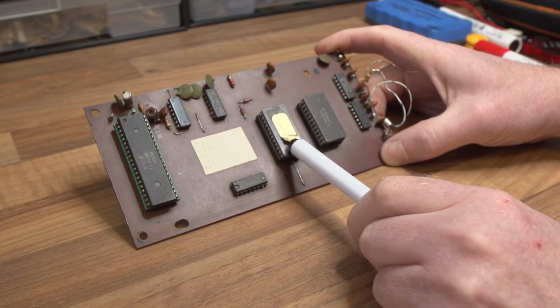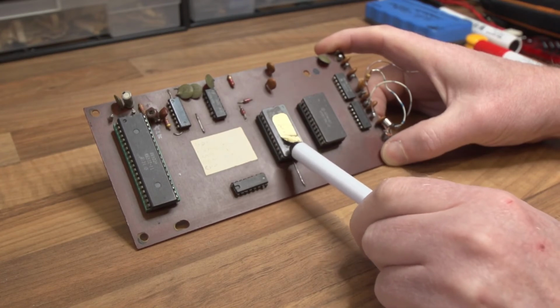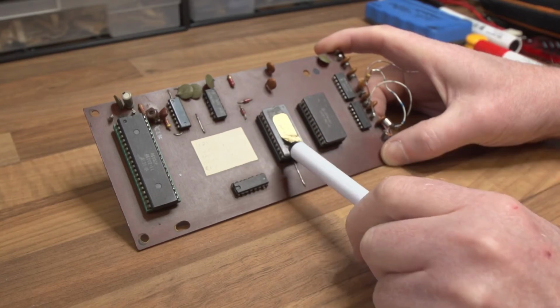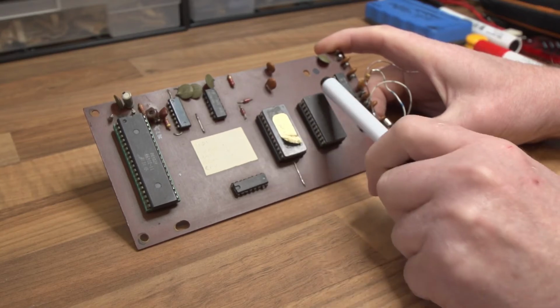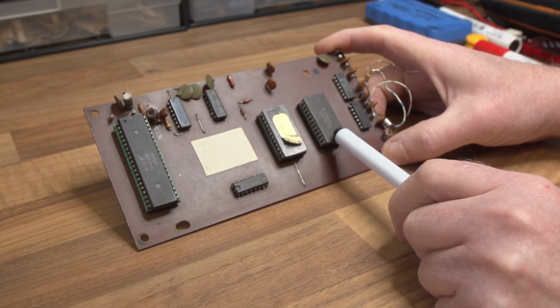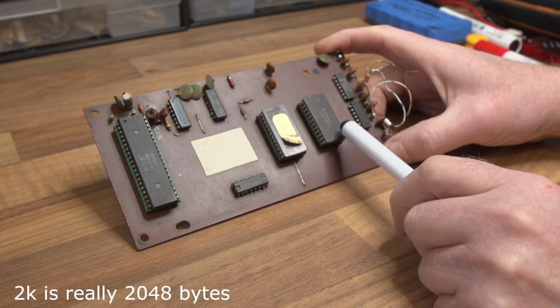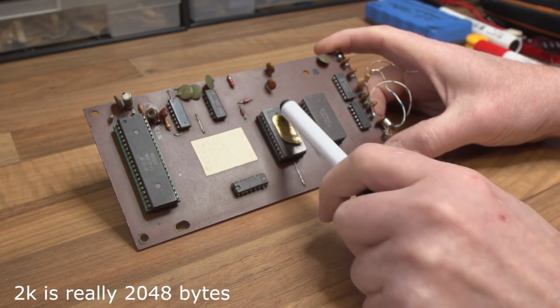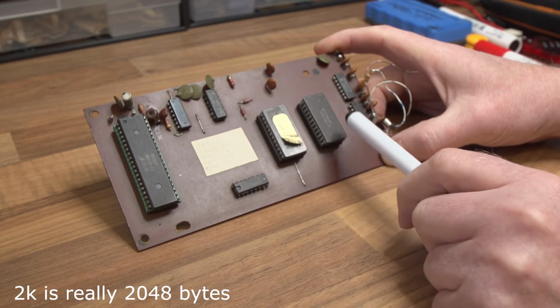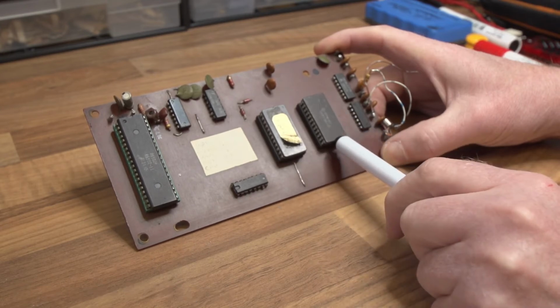So that's the EPROM holding the firmware or the program, and that's been programmed already by a programmer, an EPROM programming device. And this chip here is the RAM, which, if I remember right, is 2K, 2000 bytes worth of information. That's 2K as well actually. So that's got 2000 bytes worth of program or firmware, and that's got 2000 bytes of memory or RAM locations.